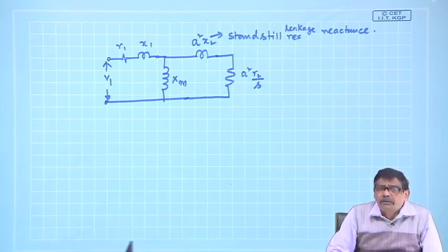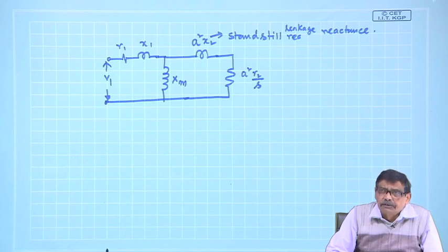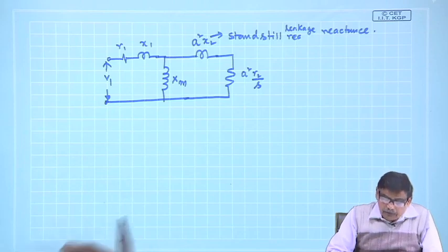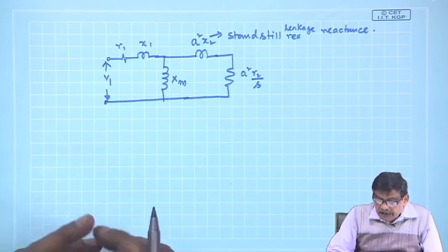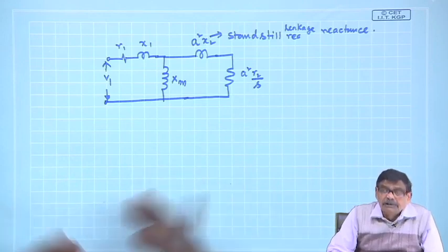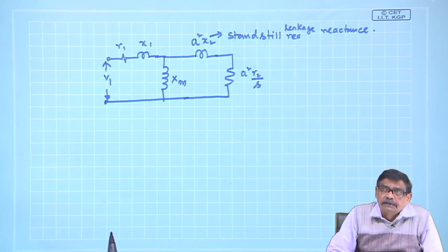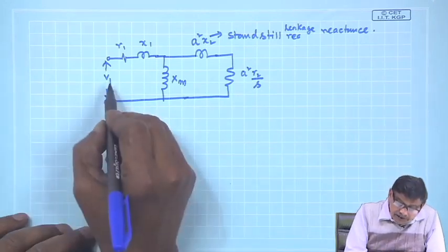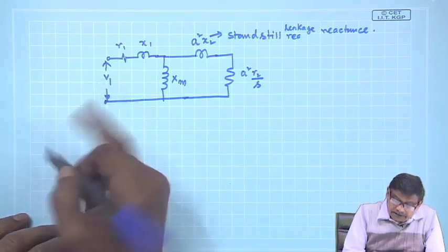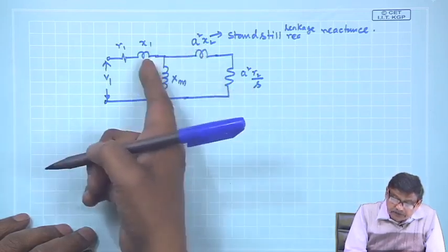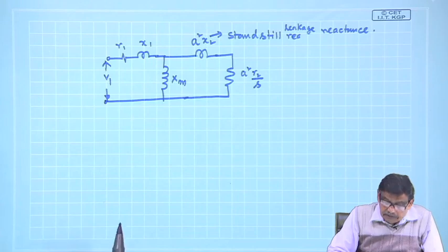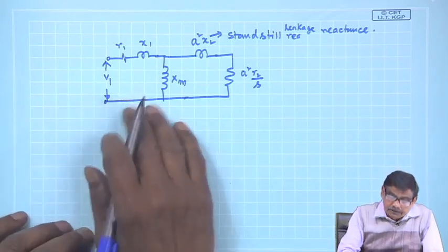We will now adopt a rather softer method to calculate the torque produced by the motor, current drawn, its power factor, how, if slip changes, what changes in the circuit and things like that. So, V 1 is the per phase voltage, all parameters are per phase, and this equivalent circuit is referred to stator.